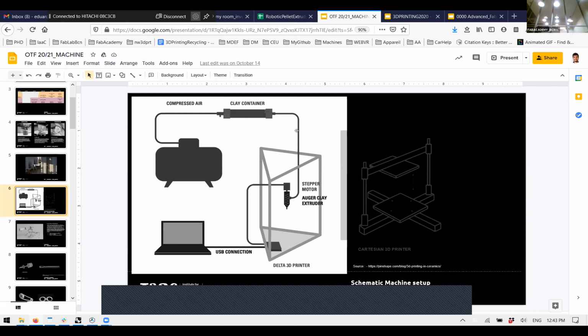You have to take into account that when you put material in, the material settles and spreads. If you have a hole of 1 millimeter, the paste is going to go a little bit to the side, so a 1 millimeter nozzle actually gives 1.2, and a 3 millimeter actually gives 3.5 in general. So you easily get 10 to 20% more than the nozzle diameter when printing. And obviously, the thinner the nozzle, the more pressure you need.